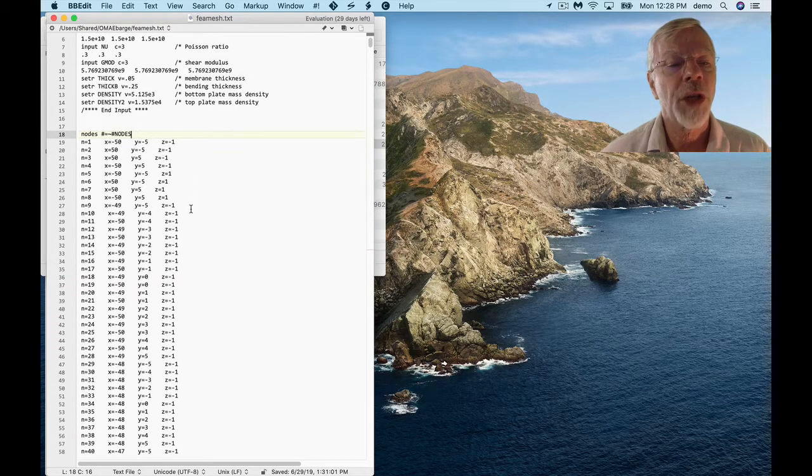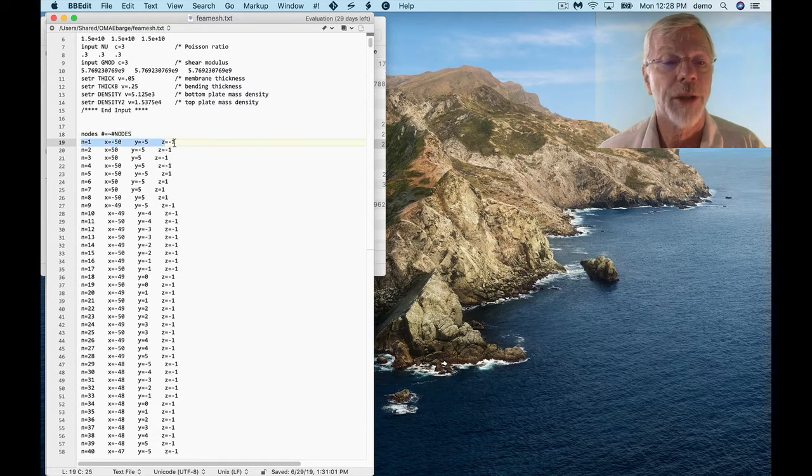And the format I've used here is what you would typically see if you're generating your mesh in an external program like a mesh generator, and then exporting the nodes and elements for input into HydroNXR. So typically each node would be specified or defined individually. I think the syntax is pretty straightforward. You define the node ID and then the X, Y, and Z coordinates.